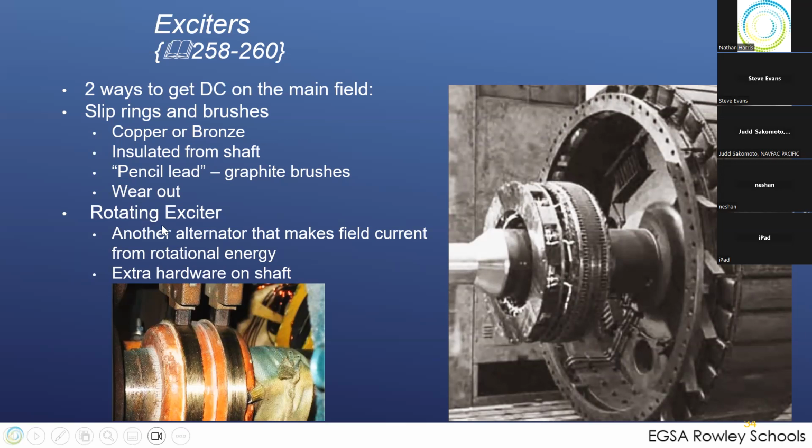The PMG source is a rotating exciter, and so there's extra hardware on the shaft. There are extra components that make this up. The shaft's more expensive, but it's got no parts to touch, so it doesn't wear out. You'll see the other windings on here. Here are rectifiers, and some filtering back here on the shaft. Here's bringing the cables to this external salient pole machine. You can see all the windings and rotors. This is a big, slow machine of some kind.